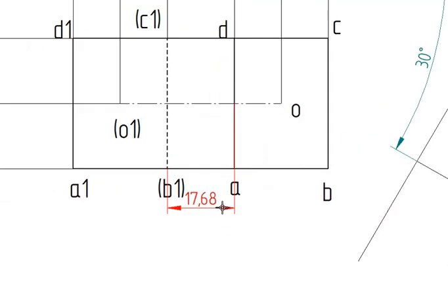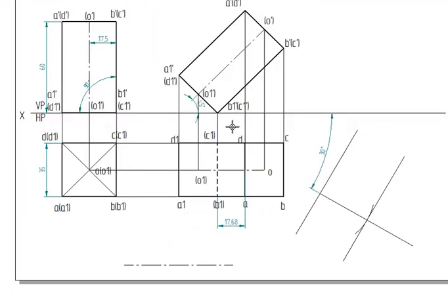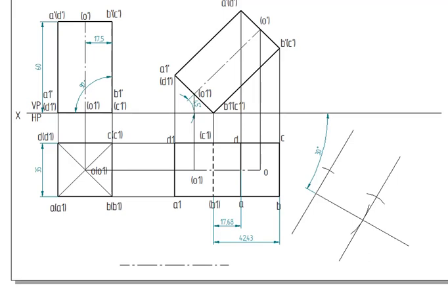17.68. I'll go for arc by center. I'm going to draw an arc of radius 17.68. Similarly from this point, when you take the compass, you don't take any 0.68, you just take the measurement of this cut arc. Now I'll take the measurement from B1 to B, which for me is 42.43. You can just directly measure it from the compass. From here I'll cut a radius.